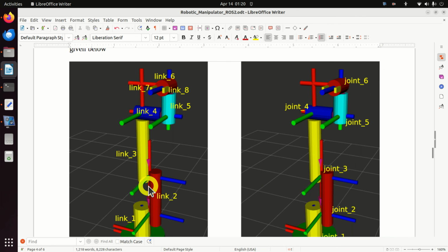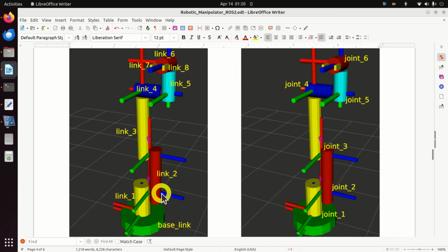Next, it's a standard convention in robotics that the rotational axis of the joint is always Z. And to follow that convention, that is to respect the standard way of describing axis, we have placed the rotational or revolute axis always as Z, and we have rotated the coordinate system such that the Z axis is always the axis around which we rotate our robotic system.